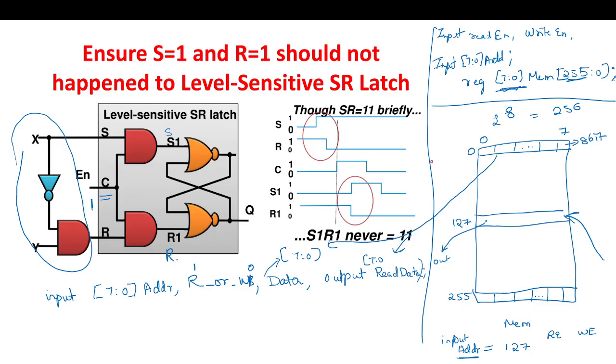So now inside this, how much memory you want, that we have to define as the register, say 7 down to 0, the memory, and how many such bits. So with this, we will get the memory which looks something like this.